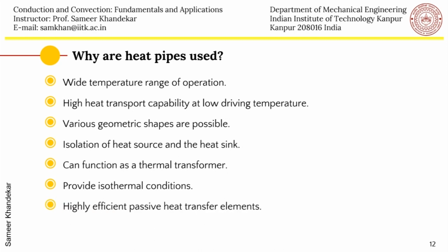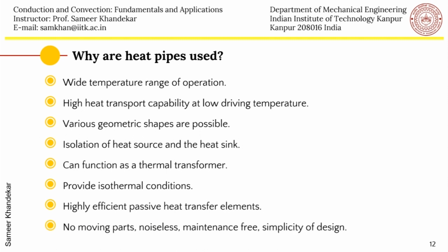And of course, needless to say, they are highly efficient passive heat transfer elements with no noise. They are maintenance free. That's why the space industry loves them. And they are simple to design. There are no moving parts. And these are some of the attributes of why heat pipes are used.